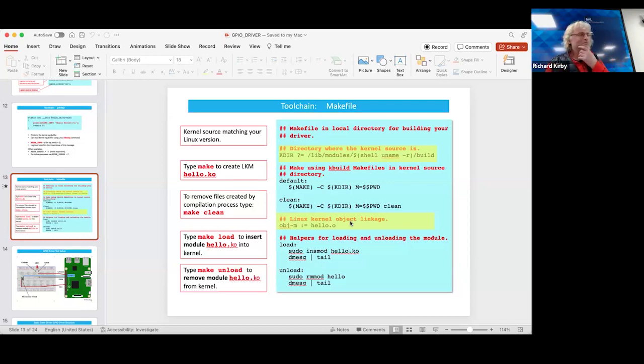This is actually the most difficult part of writing a driver for any piece of hardware. You have to get the data sheet for the hardware. With the Raspberry Pi 4, all the GPIO registers are part of the Broadcom chip, and there are data sheets for where those registers are in memory, and you basically use those addresses to write to. The GPIO pins are always in the same place. They're not going to bounce around or load up in a different place. With my GPIO drivers, I used all those register addresses from the Broadcom data sheet, which is quite easy to download now. When the Raspberry Pi first came out, they were very secretive about it, but over the years they've got less secretive.